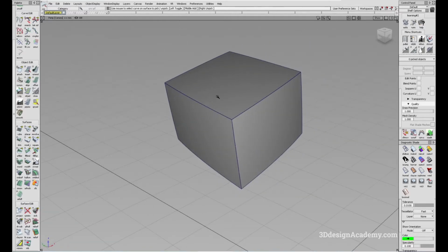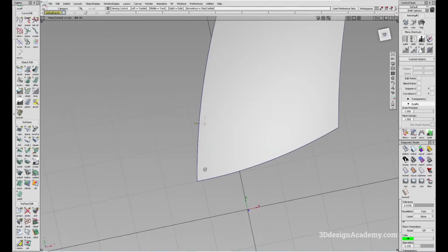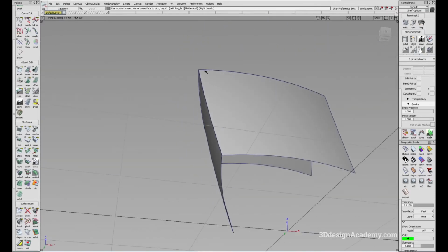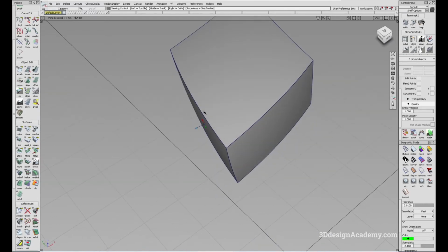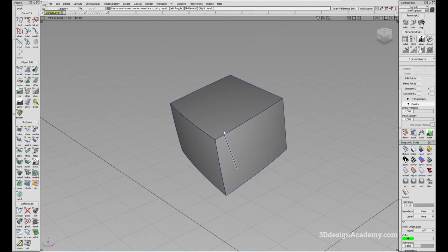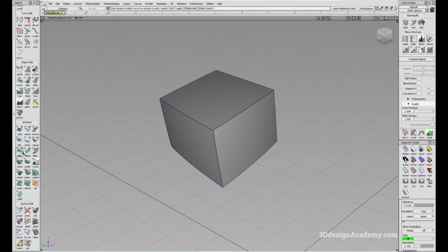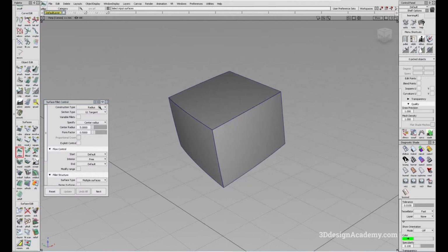You're going to have a set of surfaces that meets in the corner. It's going to have a little bit of crown. It's going to have maybe a sharper corner than 90 degrees. And now let's see if I can build a ball corner over here. So before we do that, let me just start by putting fillets on it, or the secondary surfaces.